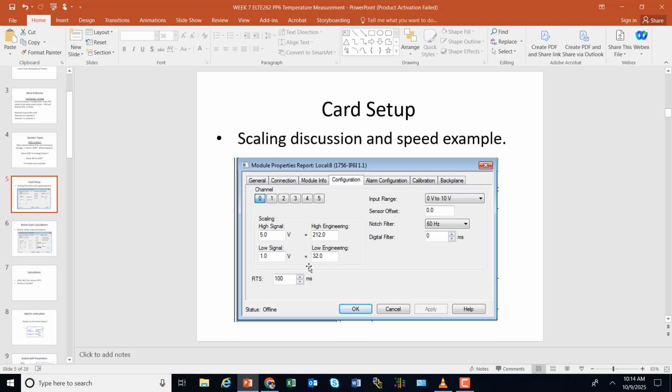And then it's doing all this math for you. You just got to be sure that you set it up right. The alarm configuration here doesn't have really anything to do with all the math that's going on here. It's just nice to be able to set some alarms, whether you set those or not. We were just showing you that they're available, but the main goal here is the configuration, and like I said, you got to configure the correct channel here. Sometimes people configure the wrong channel, and then they start turning knob 0 and nothing happens. Well, because you configured channel 1, not channel 0. 0 is 0, 1 is 1.